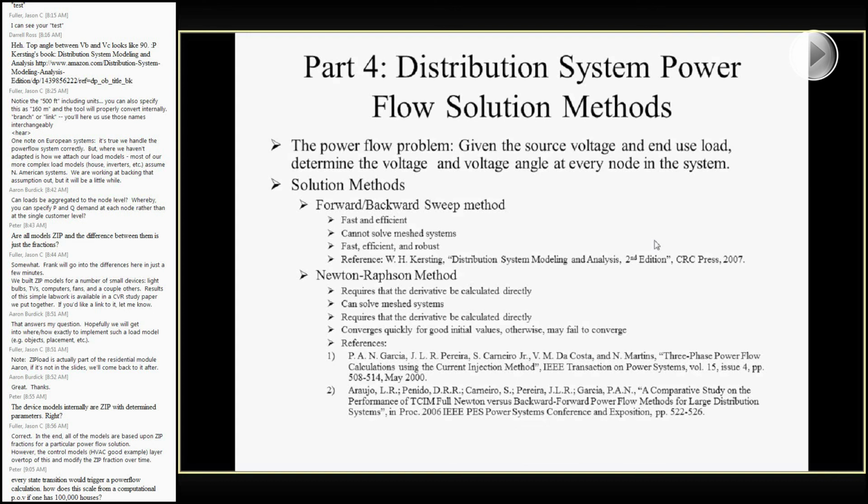We found that at about a 1 minute time step, using load models plus residential models plus all these other things that we're using quite a bit, you don't really see much of an error, something on the order of maybe 0.5% to 1% error of your energy consumption over the entire annual simulation. But you also speed it up by 60 to 120 times. So it's a bit of a trade-off there.